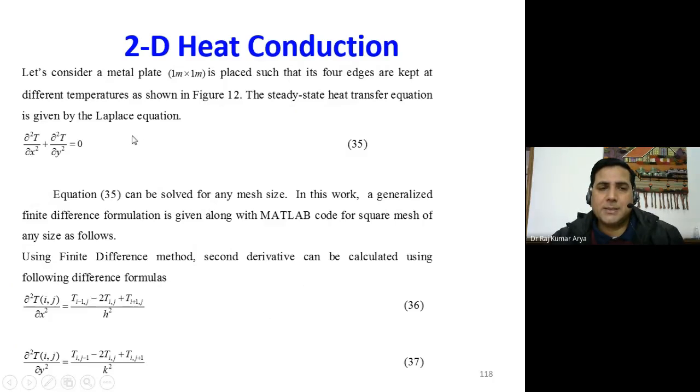So for that case, we want to convert it to two-dimensional, because we have a metal block. So we are considering for the time being a two-dimensional one. It can be solved for three-dimensional, but for the time being we are solving it only in the two-dimensional case, without any generation within the materials, and in steady state conditions. So the rest of the terms would vanish from here. So this is the equation which needs to be solved. It is a partial differential equation, and this format of the equation is popularly known as the Laplace equation.